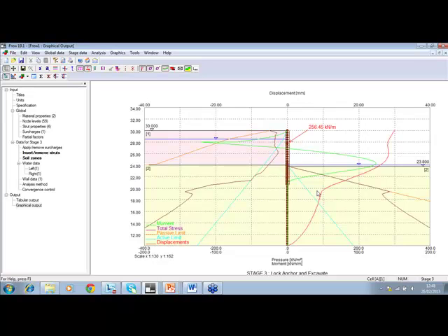And so the designer might look at this and think, maybe I could do with making the toe a little bit longer, maybe looking at putting a berm in here, for example, changing the level of the anchor to compensate accordingly. So, having looked at the outputs and understanding the way your retaining wall behaves, you can better understand what to do at different construction stages. So Frew allows you to do that. It gives you the power to understand better what's going on with your retaining wall.